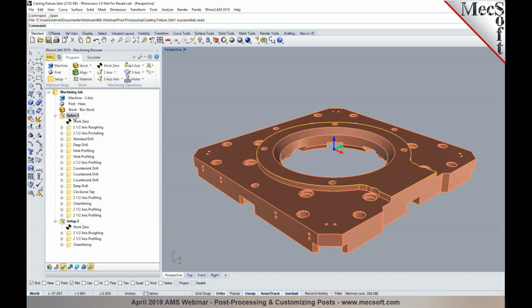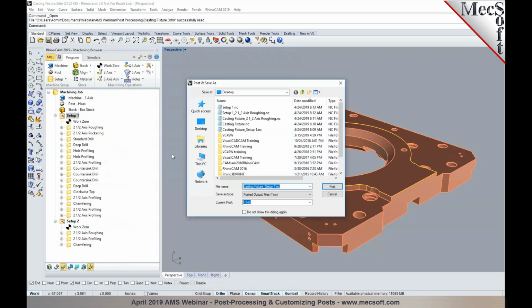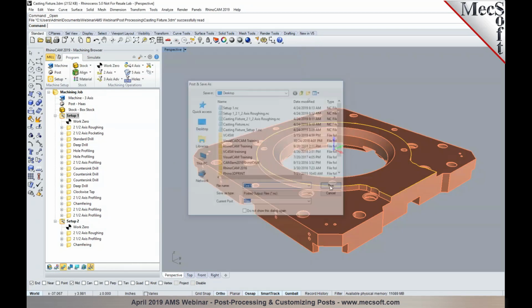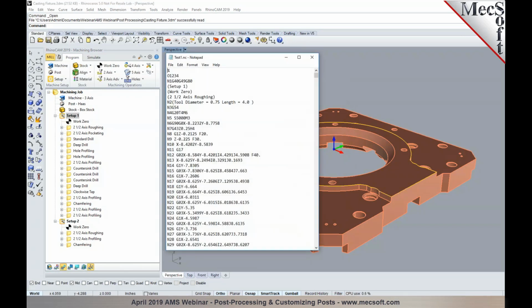Now one thing to be noted here is when you right click and post, you could still change the name of the file to what you like. The default name, what it lists or displays here, is what is defined in the naming convention. However, you can still change it, for example, I could say test1 and post it to assign your own name for the posted file.